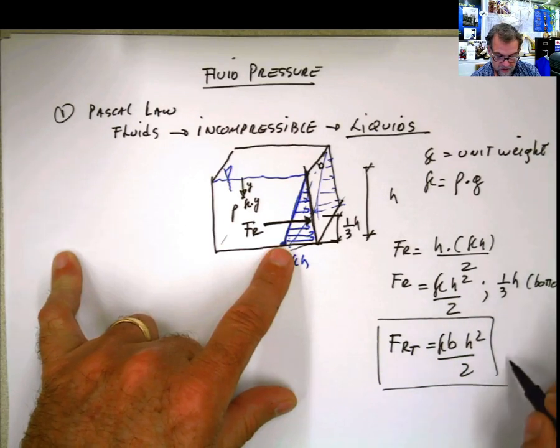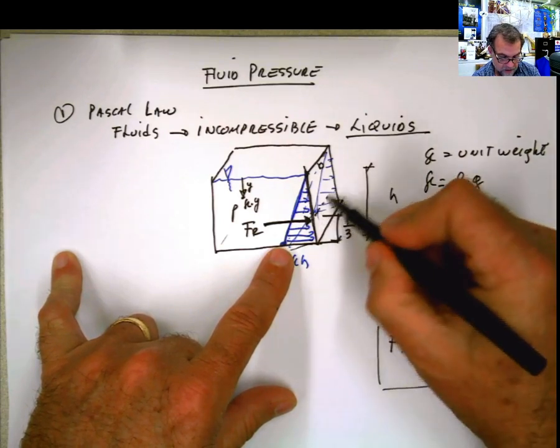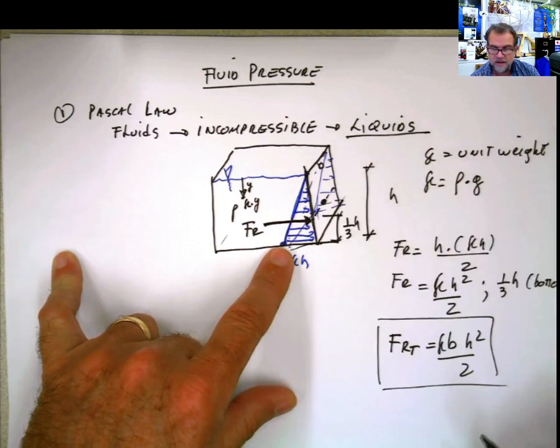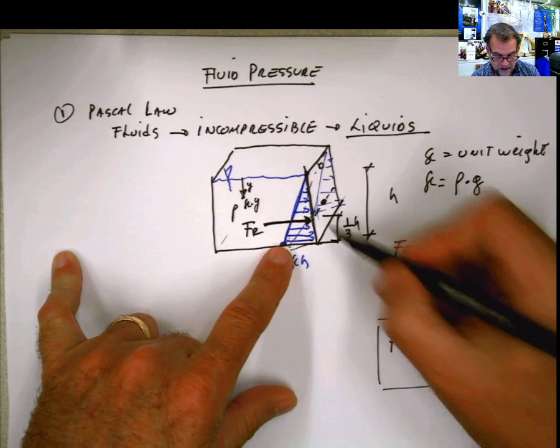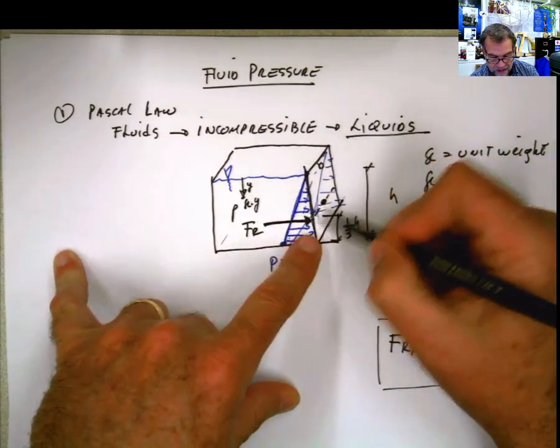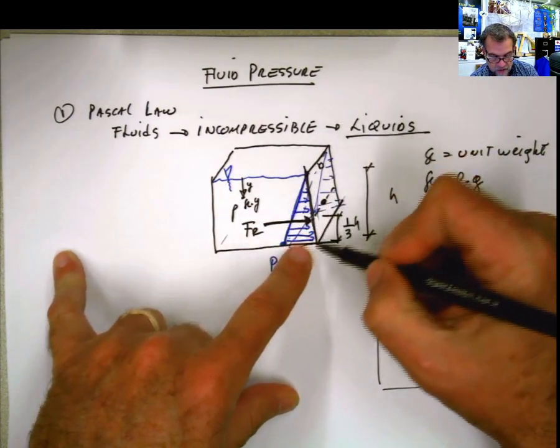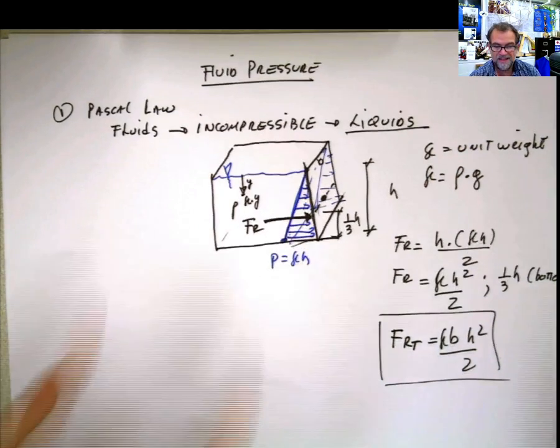and if it's this one, it's going to be at the same level location, but it's also going to be at the center of the surface. So it's going to be just two coordinates in this case. If this is rectangular, well, it's going to be half of the distance in this direction and 1/3 of H in that direction. This is the basic principle.